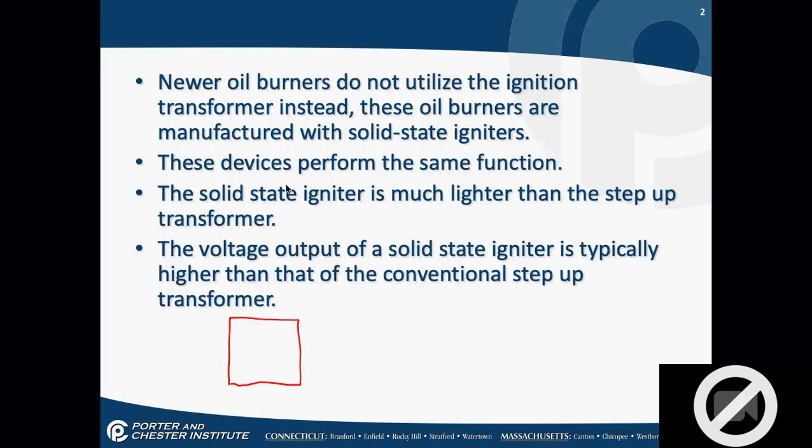Okay? The solid state igniter is much lighter. If you hold these in your hands, the old style transformer is going to feel like a brick, compared with the solid state one. Very light. The voltage output of a solid state igniter is typically higher than that of the conventional step-up transformer.